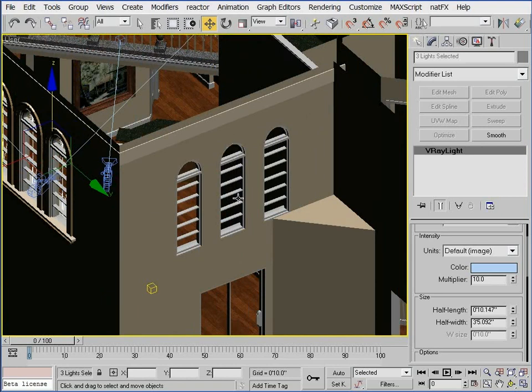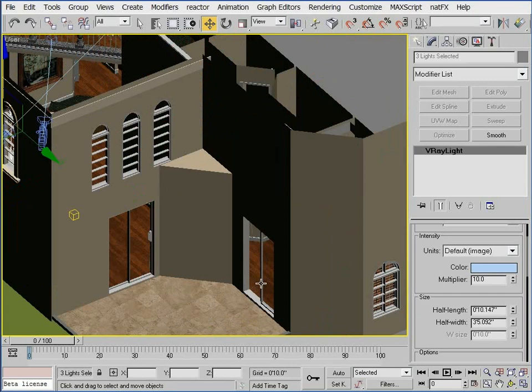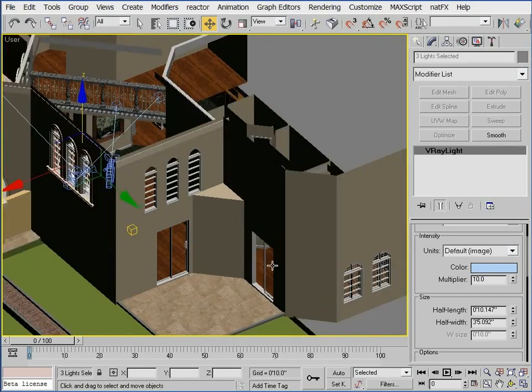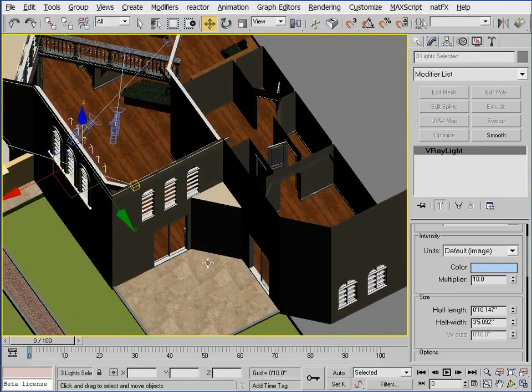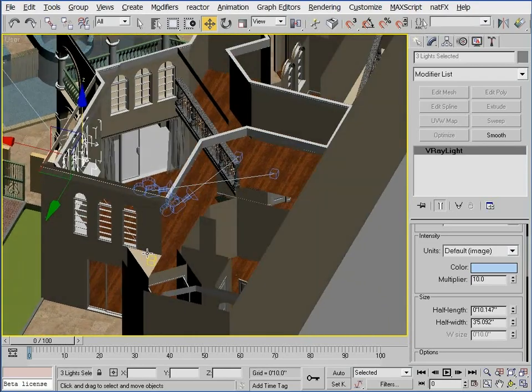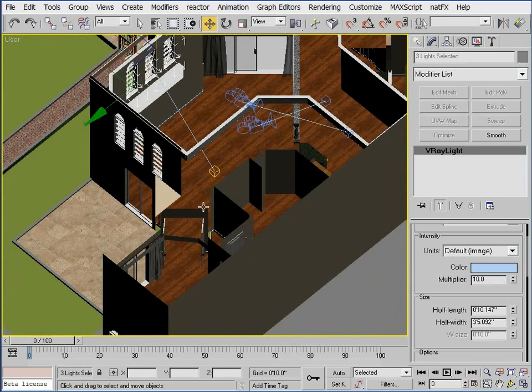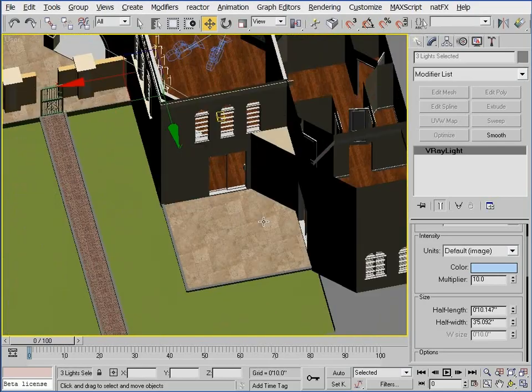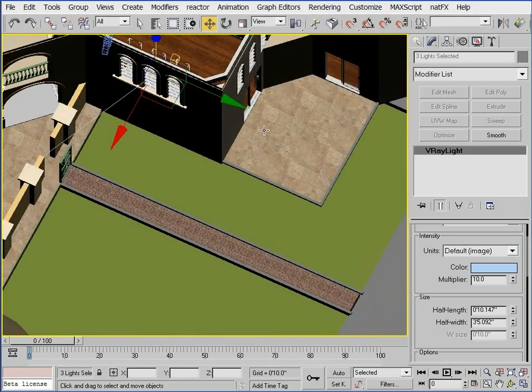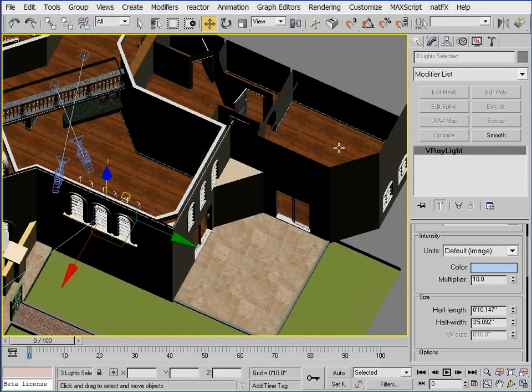and because of that, they should clearly have a smaller intensity value. But the reason I want to work on these lights next is because they're part of the same room. Although the windows here in the bedroom are facing the sun just like the first 3 windows I placed, the only way the light in the bedroom will affect the living room is by coming through the bedroom door. And this bedroom door is fairly small compared to the entire amount of space in the bedroom. And this simply means that adding a light in the bedroom will have a negligible amount of impact on the total illumination in the living room.